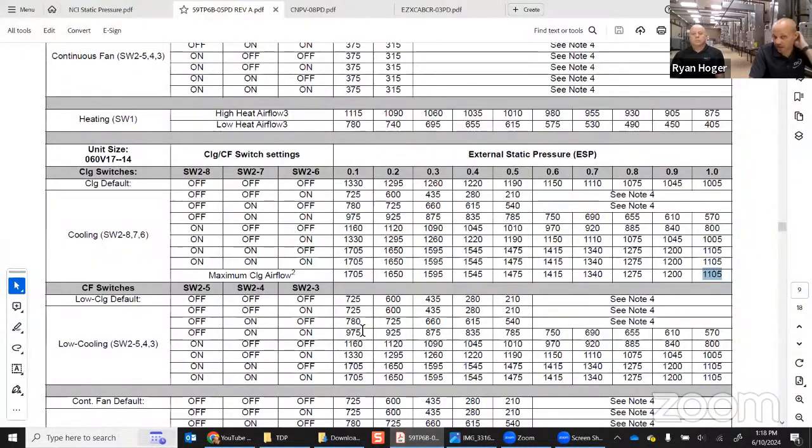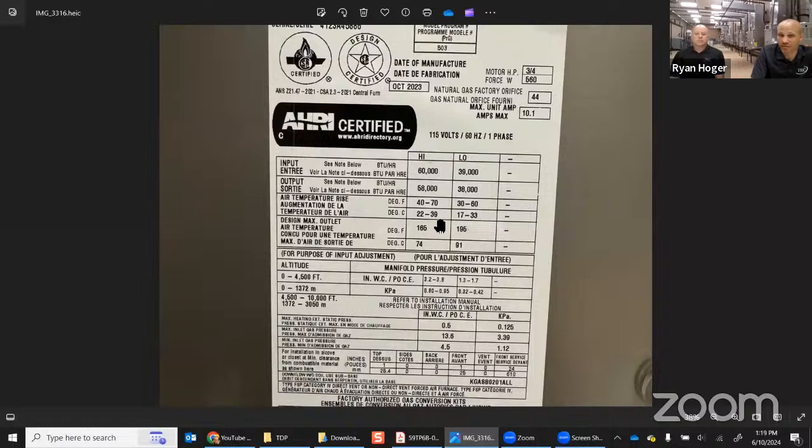When you're in cooling and you add an evaporator cooler to the system, that changes it up a little bit. But over here, they're testing your furnace here at 0.1, 0.2, somewhere in between there, depending on the size we showed you on the other one. And they're expecting you to keep it below the 0.5. So that's actually printed on the tag of every unit. I think almost every manufacturer uses the exact same 0.5. It'd be rare to see something that's not 0.5 for a residential furnace. Doesn't mean you can't operate at 0.6. It just means as you get further past 0.5, bad things happen.